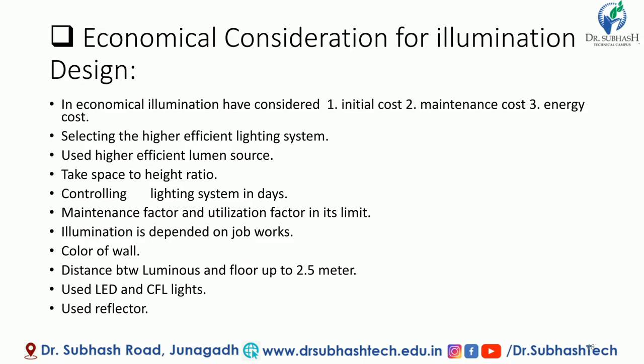Right. Following are the factors for the economical condition. First one, you have to select a higher efficient lighting system. Second one, use a higher efficient luminous source. Third one, consider the space to height ratio. Fourth one, control the lighting system in the daytime, which means in the day you can take the advantage of sunlight, right?